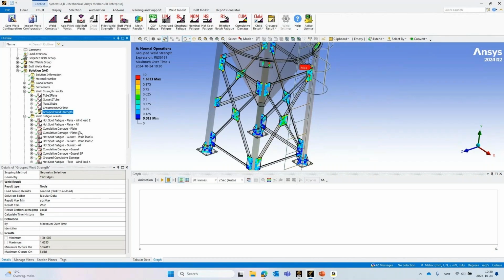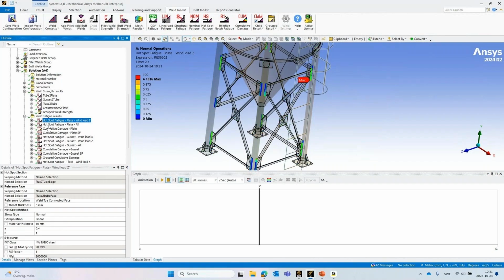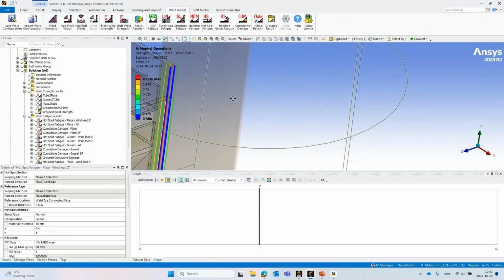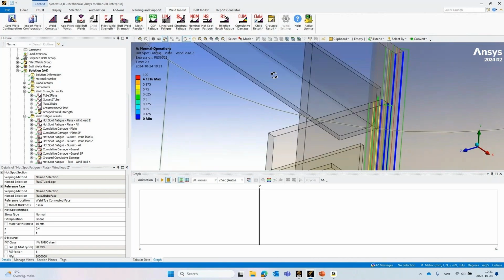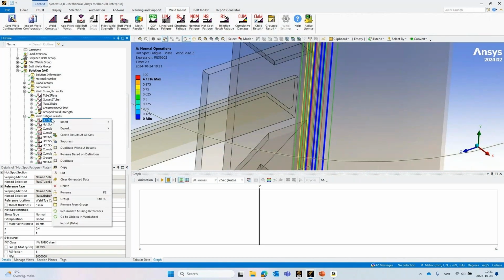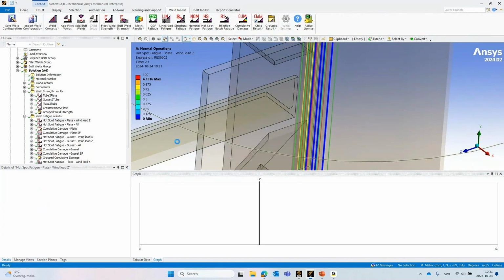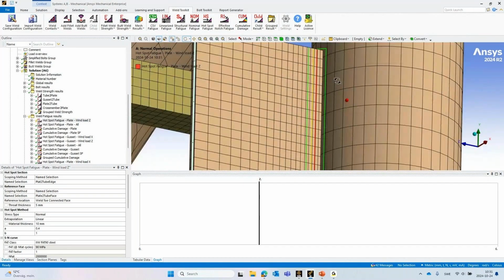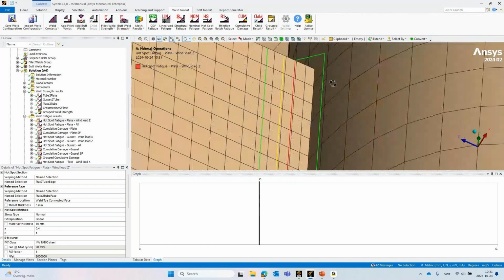Next up is the weld fatigue feature. So as mentioned here, I was using hotspot, and when you set this up, if I clear this result to demonstrate, and then we turn on the mesh, it visualizes my weld because I selected the same scoping as for the weld and defined this to include this weld to offset.